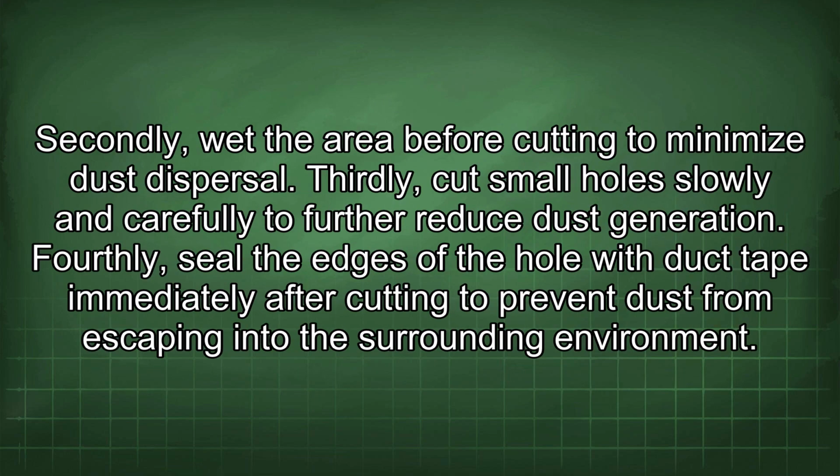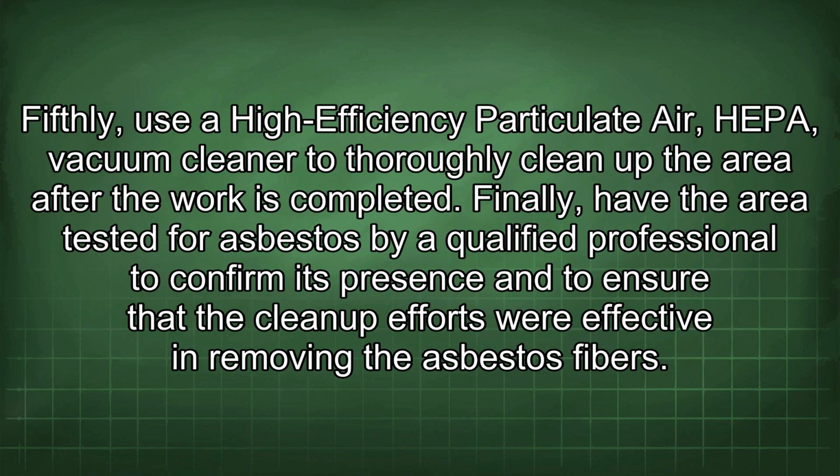Secondly, wet the area before cutting to minimize dust dispersal. Thirdly, cut small holes slowly and carefully to further reduce dust generation. Fourthly, seal the edges of the hole with duct tape immediately after cutting to prevent dust from escaping into the surrounding environment. Fifthly, use a high-efficiency particulate air (HEPA) vacuum cleaner to thoroughly clean up the area after the work